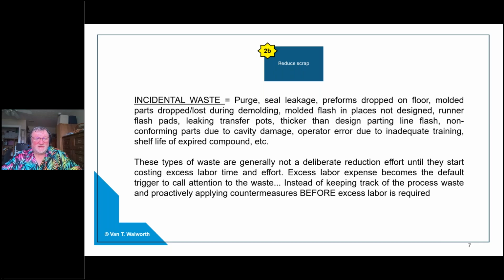And then there's the question of how much purge needs to be there, especially when it's a manual purge, when the operator is the one that's going to push a button and let some rubber come out. How much rubber should they make come out? Well, often maybe only 2 inches of rubber would have been enough to purge, instead of a whole string of rubber that was a lot at different times.